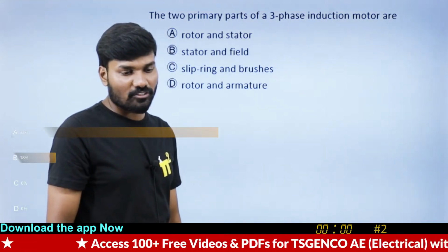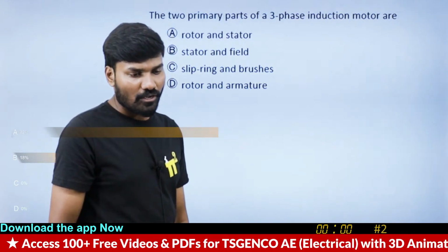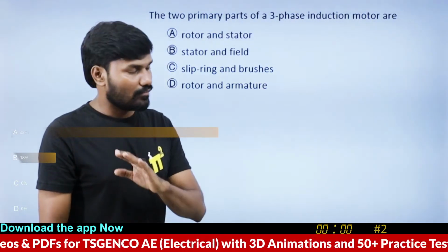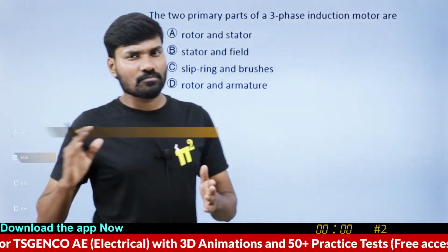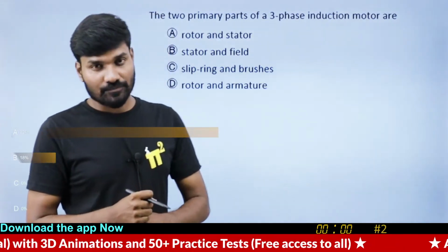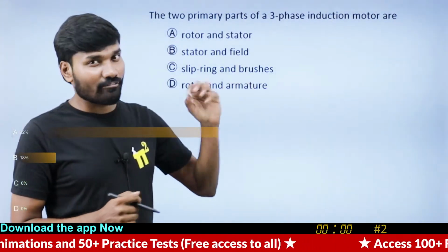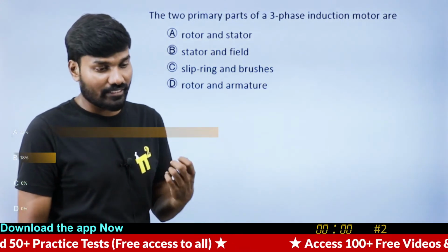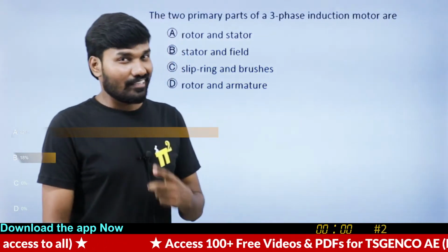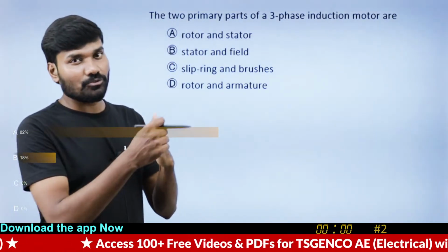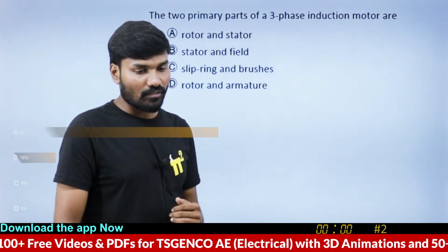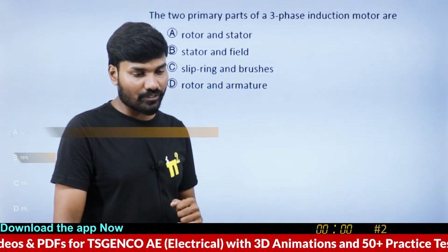Principle of induction motor is also similar to synchronous motor. Praveen, that's absolutely not right, dear. The principle of operation of a synchronous motor is completely different. It works on the magnetic locking principle. An induction motor will never work on the magnetic locking principle. There, in some way, Lorentz force will come in case of induction. In case of synchronous, attraction force due to the magnetic locking will come. So there is a huge difference. Okay, so I hope you are clear what we're trying to say.